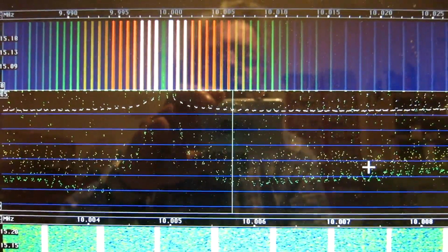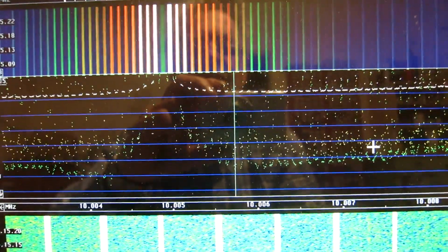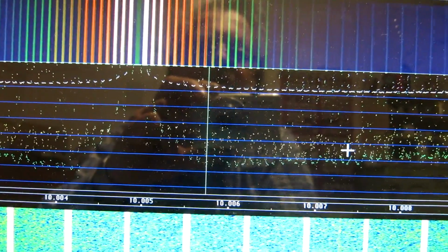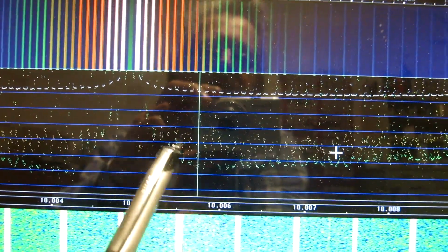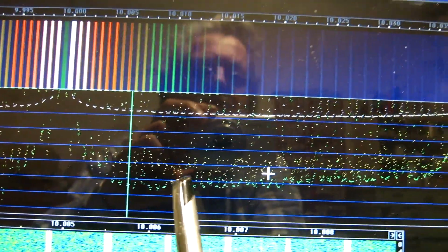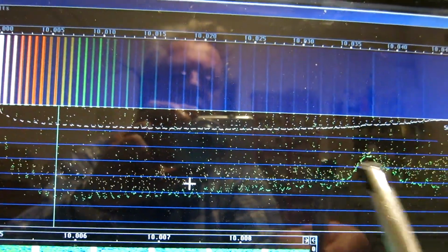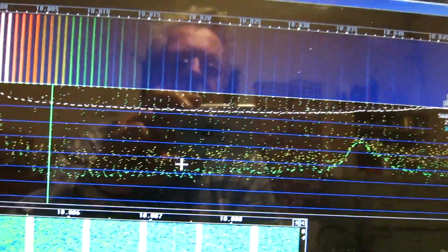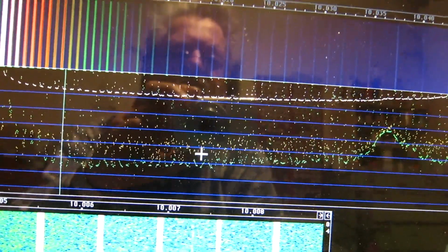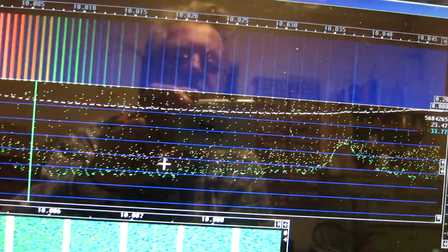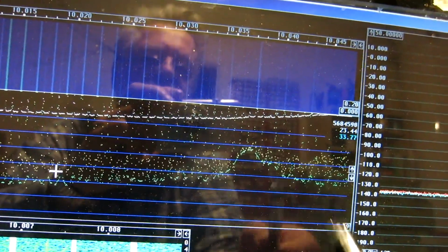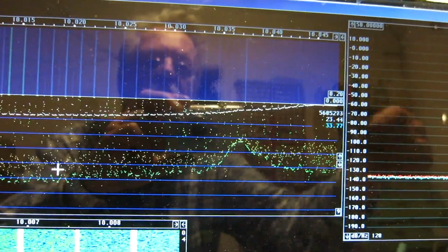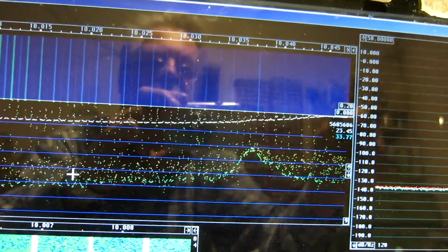Now it has been running for a long time. The result is a little unexpected. There is a sweet point here. This is obviously sideband noise. The reason for the slow slope upwards is unknown to me. Maybe it could be phase noise on the sampling clock of the sound card. And this structure here, it's a strong signal. It's only 10 decibels below the noise of the sound card.